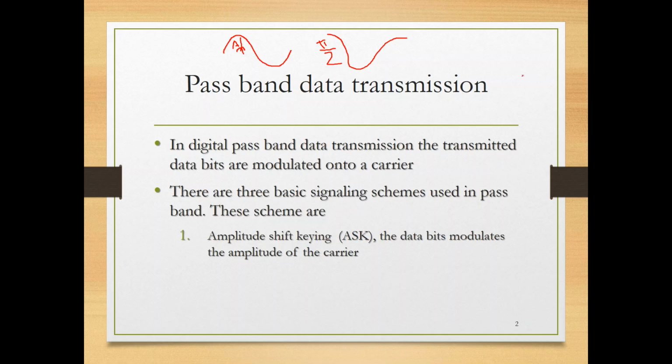You can make it a phase of pi/4. So you can change the amplitude, the phase and the frequency. For example, this is of frequency F0. If you increase the frequency, it will oscillate more within a certain period. So you have these three key properties of your sinusoidal signal that you can change.